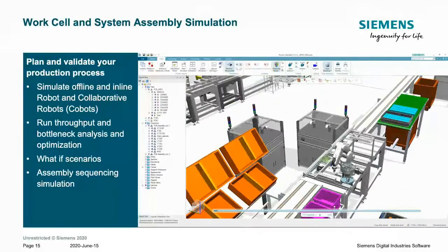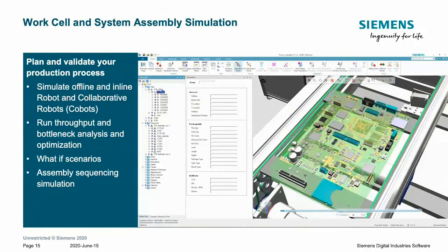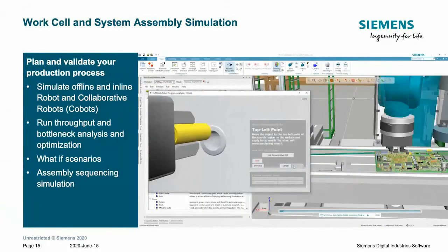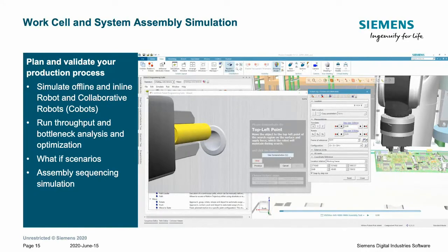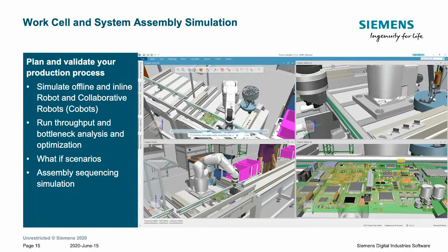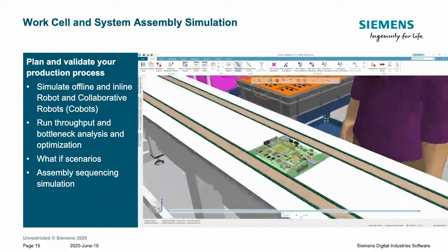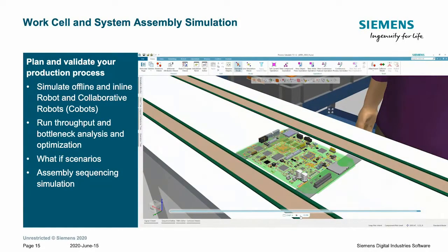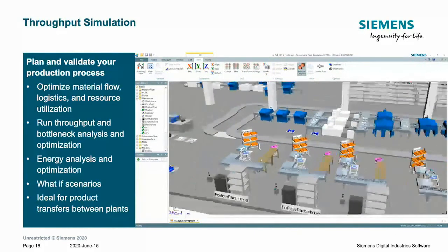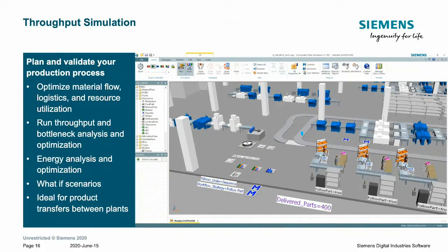As I mentioned earlier, the use of cobots and robots working side by side may be quite effective. Programming the new generation of these universal robots has also become close to drag and drop, as shown in this video. This allows factories to do what-if analysis in the areas of material flow and simulate delivery systems, identify bottlenecks, even monitor productivity levels and resources. A discrete event analysis based solution is probably the best way of simulating manufacturing environments such as this. In addition to simulating the specific robots or humans in the cell, we can also simulate the material delivery and the overall throughput of cells by optimizing material flow and running various what-if analyses on those cells as well.